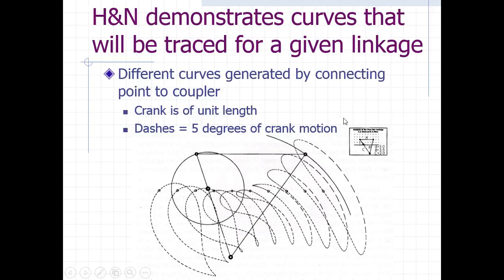You can see that if you focus in here on this guide, where we have 1 representing the crank length. A, or the coupler in this case, is equal to 3 times that 1. The rocker here, represented by B, is equal to 3.5. And the ground length between these two positions, C, is 2 times.